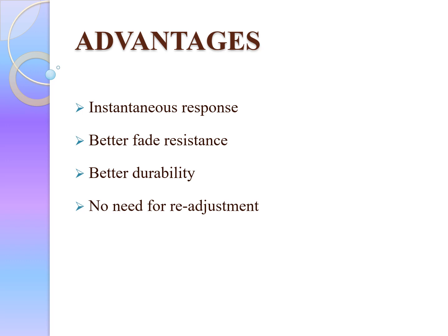And fourth one is no need for readjustment. In this, the viscosity of hydraulic fluid changes as temperature changes. This may be because of climate, season, or heavy duty. The high pressure gas compensates immediately and automatically for changes in viscosity. And these are all the advantages of the nitro shock absorber.